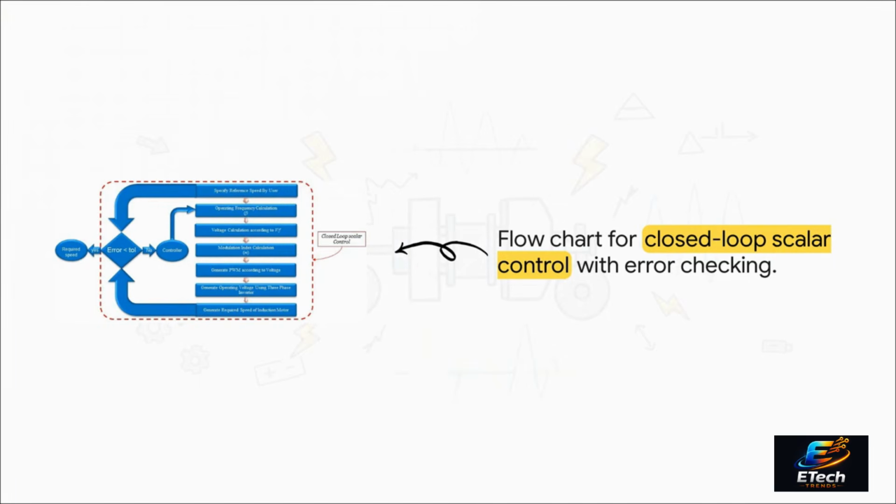Yeah, that hope for the best approach is exactly why high-accuracy applications like modern passenger EVs demand closed-loop control. The critical component here is that decision point checking if the error is less than the allowed tolerance. The system is continuously checking the actual output speed against what the user requested. If the error drifts outside that tolerance, it routes right through a controller to course correct immediately.